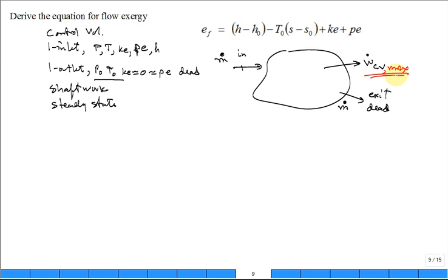Okay, that's the goal. Well, could we also have some heat transfer into the system? Yes, you could. Let's leave it in the traditional sign convention, Q dot in. But because we don't want that Q dot to be adding or removing any exergy, we're going to do an exergy balance. You could have some heat transfer, but let's say it happens at the boundary temperature of the dead state, such that the exergy in or out with that Q dot is 0. Make sense?